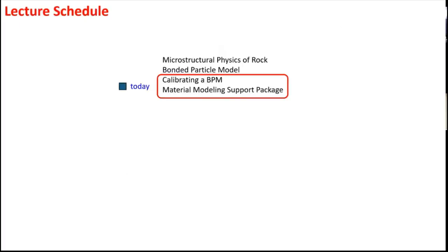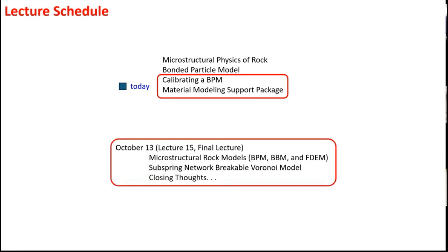Okay, today we're going to really delve into calibrating a bonded particle model, and we're going to do most of that work using a FISH environment that's been created to help support creating bonded materials, and then also performing laboratory tests, direct tension and triaxial compression. And then the final lecture will be next week.